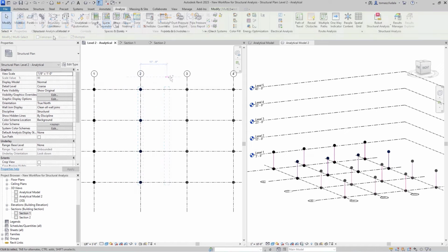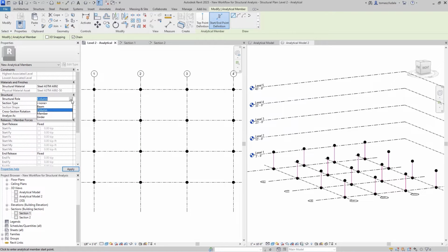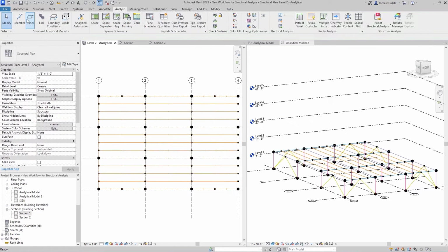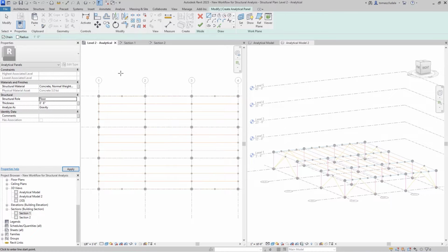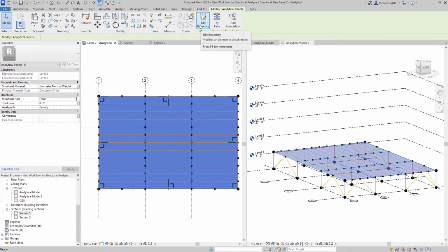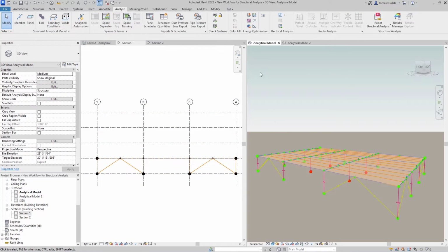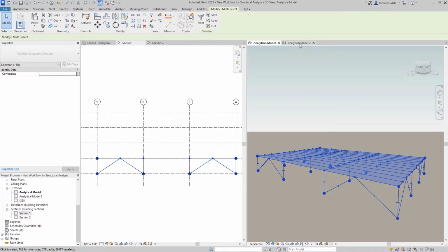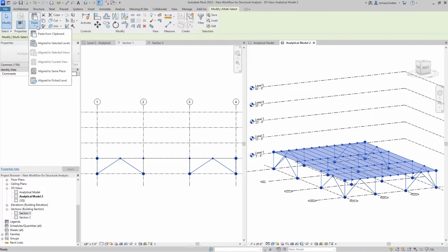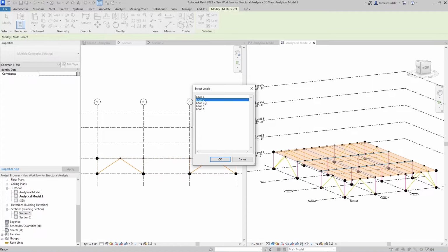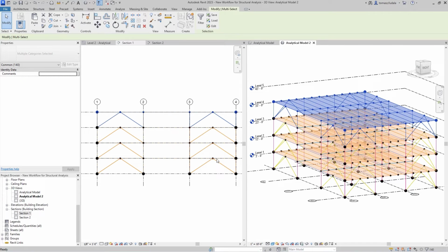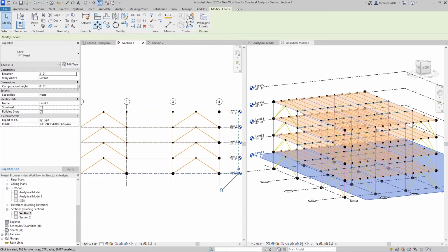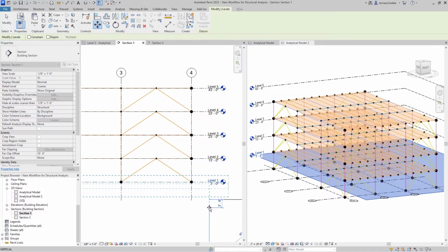As the analytical model is now completely autonomous, you can choose to initiate structural analysis workflows from Revit without any physical context. For example, when starting a project from scratch, you can focus exclusively on analytical modeling, just like you would in traditional analysis software. In Revit, analytical elements are fully parametric and are associated with grids and levels, enabling you to control element positioning using these datums. This new approach to structural analytical modeling offers many benefits to structural engineers.